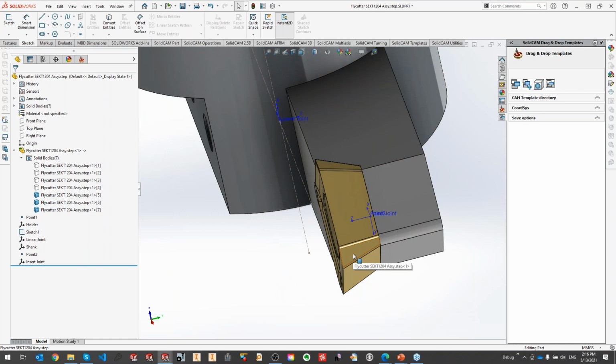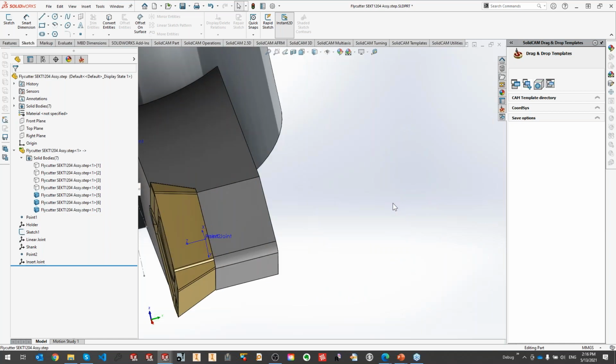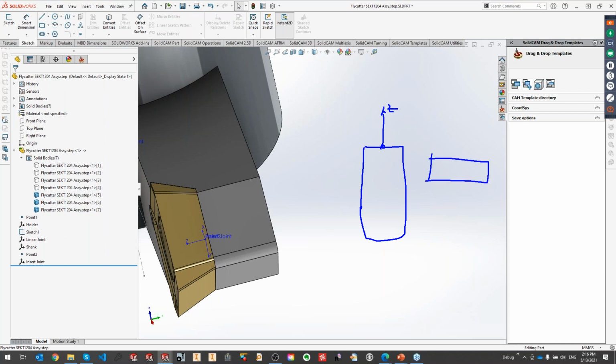I would dare to say now that, if you remember my presentation where I said that if you have an endmill here, always define your coordinate system like this in the Z, the same rule you should apply also for the insert. So even though you have an insert, please define the Z-axis over here. In the previous webinar, we defined it over here. It's not so bad for milling, but for turning, it will be devastating. Okay, so I will give you more info about that later.